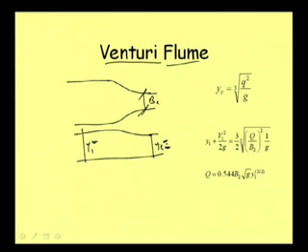Now, a more important point is that to form critical depth here, we know the critical BC, but if we further reduce this width, still the flow depth here will remain critical, upstream will only rise. And for a measuring device, if upstream is rising, we do not have any problem. We want to get the discharge based on the measurement that we will be conducting at the upstream point. And as such, we know this relation that critical depth is equal to (q square by g) whole to the power 1/3, or cube root of q square by g.